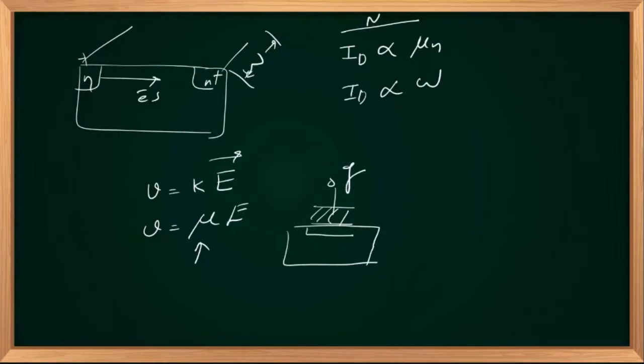The created N layer, we will call it the inversion layer or N channel, or the electrons accumulated at the bottom plate of your capacitor. This is SiO2. So it will have a particular value of capacitance, we'll call it the oxide capacitance, Cox.